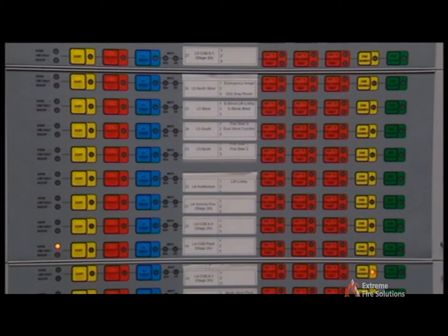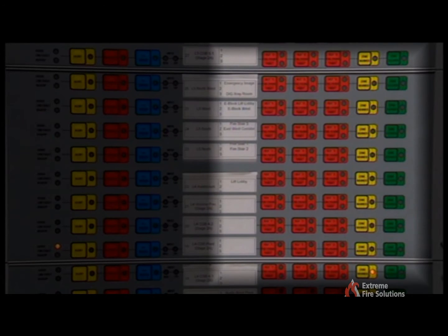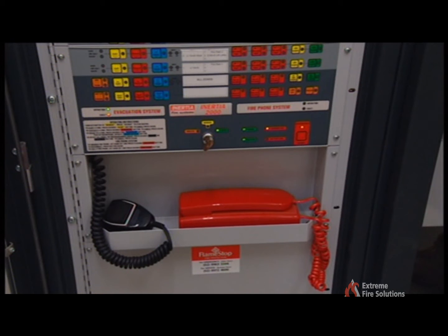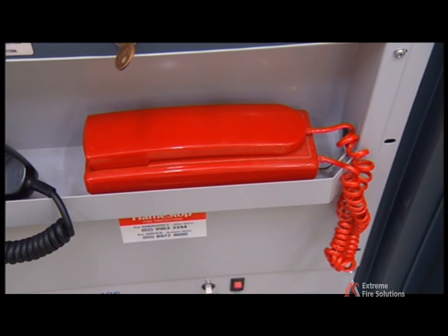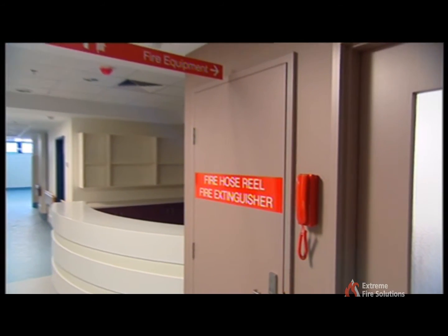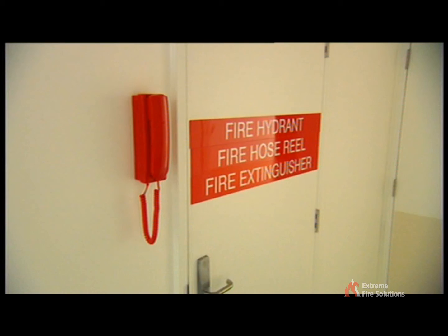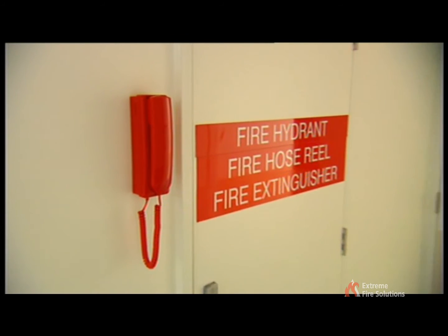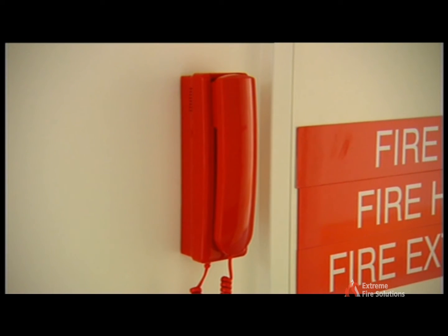The MECP comprises two distinct and separate systems: the emergency warning system and the emergency intercom system. The EIS provides telephone handset communication between the MECP and field-mounted warden intercom point WIP handsets. This system allows the fire warden or the fire brigade to communicate with floor wardens and to control evacuations.